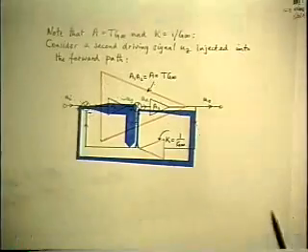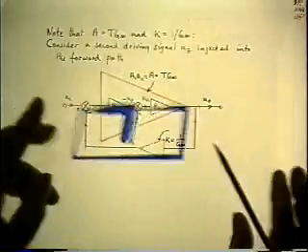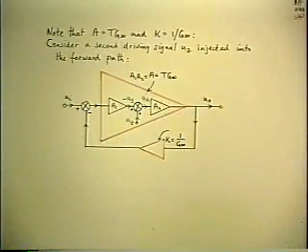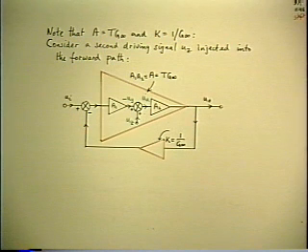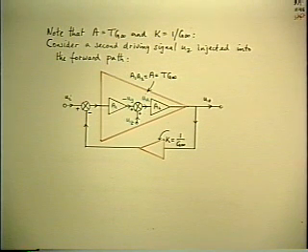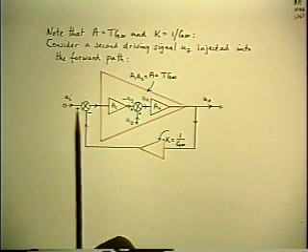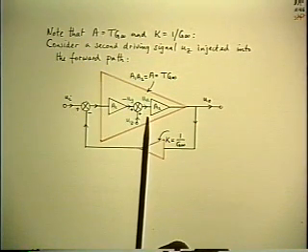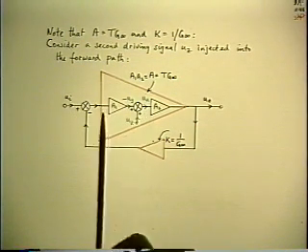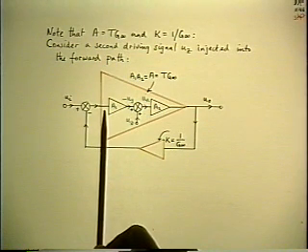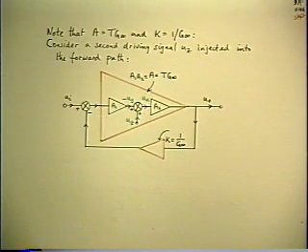You can extend that same process to find the g infinity. To find the g infinity, well, let's think a moment about what setup you could use to find g infinity. G infinity is the ideal closed loop gain if the error signal is 0. How can you establish a set of signal conditions in order that you can make the error signal 0? Null double injection.